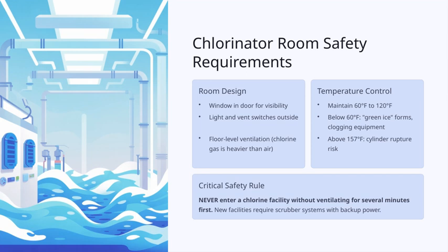Now, a key safety rule that I want to emphasize: never enter a chlorine facility without ventilating it first, and this should be done for several minutes. Proper ventilation is essential to clear any residual gas. For new facilities, this process should include scrubber systems with backup power, ensuring continuous safety even during power outages. Following these precautions helps protect everyone and keeps the system operating safely and efficiently.